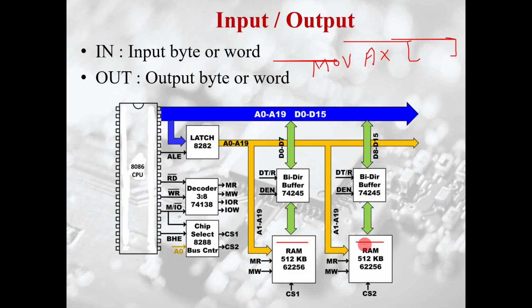In that case, suppose I write here 1000, some memory location, this is just the offset. So some memory location ending with 0, this 8-bit information will be here, and from the next memory location also data needs to come. So when I write some instruction like this, the CPU also sends information that now we are talking about 16-bit information.